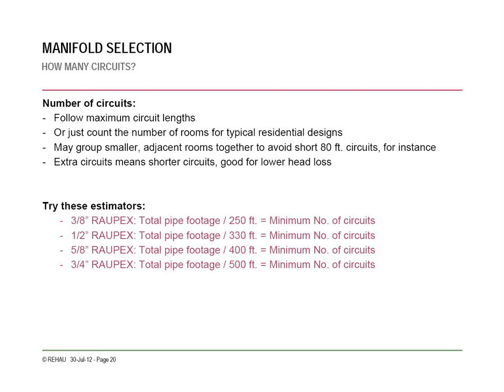So the key things to consider here are first your square footage, obviously, but then the flow that each circuit is going to see, which is dependent on how many you have and how long they are, and then if you're using glycol. So here are some pretty standard methods. I would say these are for water only and for radiant flooring, radiant heating versus snow melt.